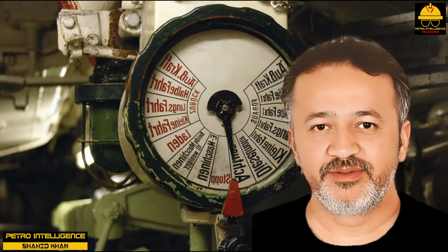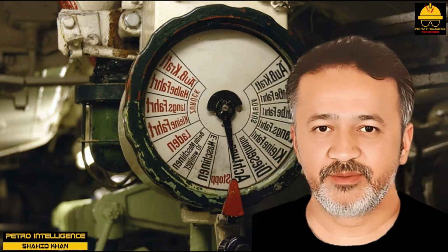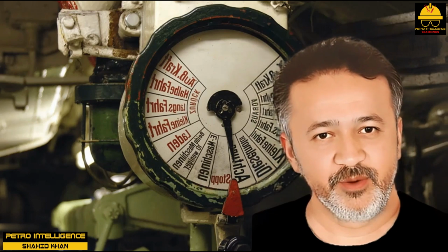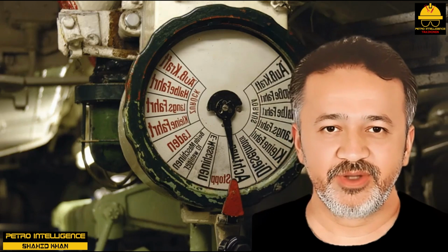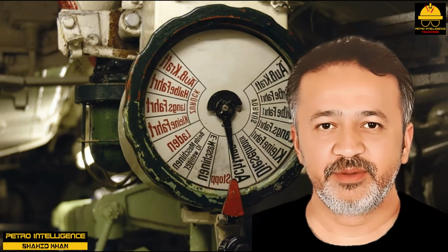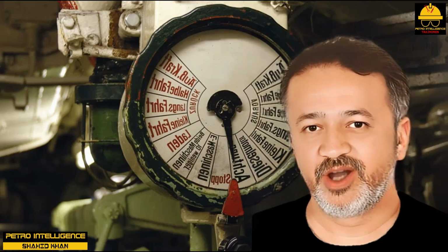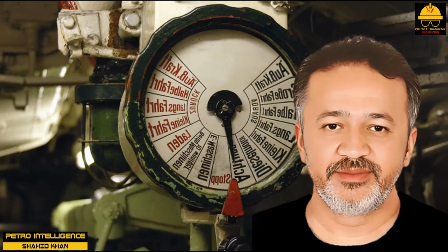An interlock is a device designed to prevent damage to equipment and personnel by stopping or preventing the start of certain equipment if a preset condition has not been met. A permissive is a special type of interlock that controls a set of conditions that must be satisfied before a piece of equipment can be started. Permissives deal with startup items, whereas hardwire interlocks deal with shutdown items.